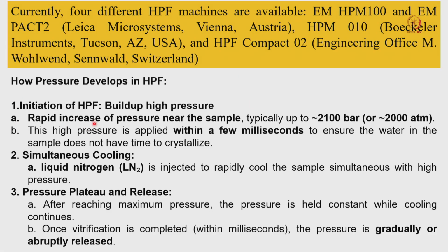So, what is the take home message? Rapid increase of the pressure near the sample area, typically up to 2100 bar or 2000 atmospheric pressure. This pressure will be applied within a few milliseconds. The important point is that a few milliseconds ensures that water in the sample does not have time to crystallize. So, it should not form crystalline ice.